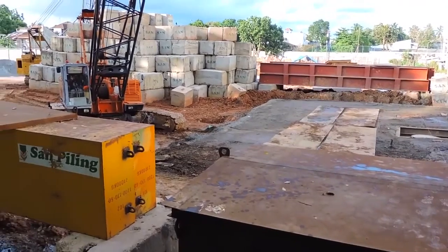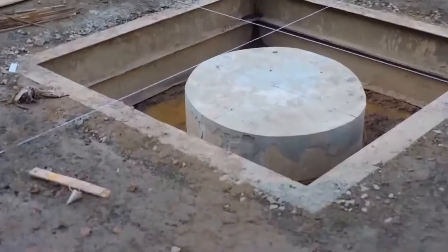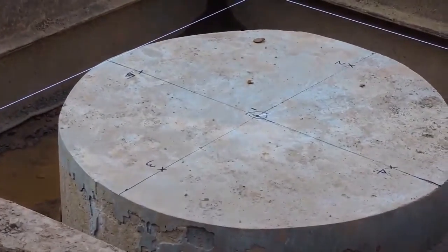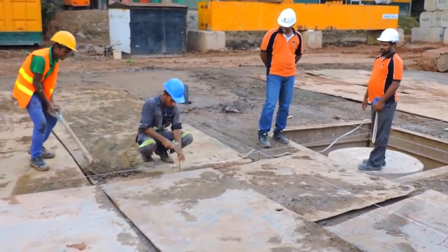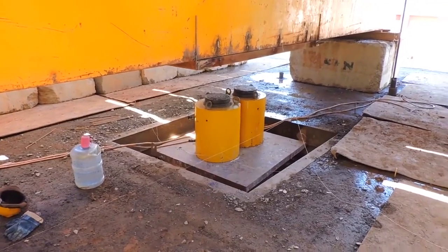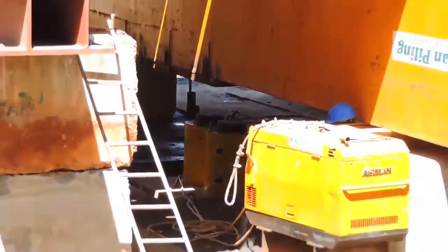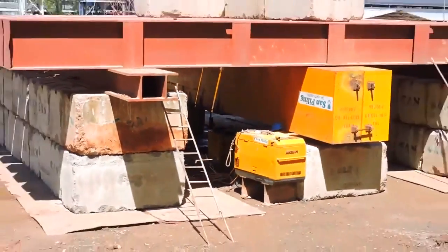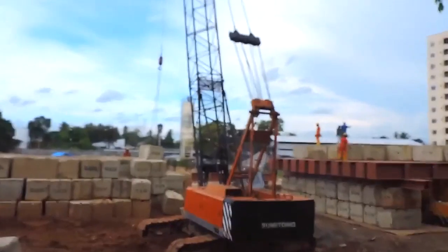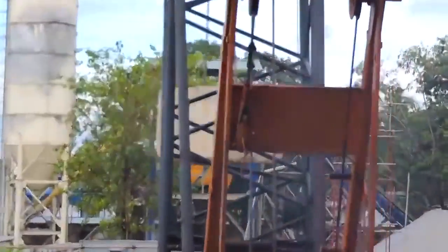After casting, piles are tested to check whether they can function properly. The maintained load test, which is known as MLT, is the most expensive and time-consuming test in piling work. For that, the surface near the pile should be improved so that it bears the surcharge weights of the concrete cubes. Then the jack is fixed over the center of the pile and the main beam is kept over the jack. Next, sub-beams are kept over the main beam, and finally the load cell is fixed between the jack and the main beam, while fixing the dial gauges to the pile.